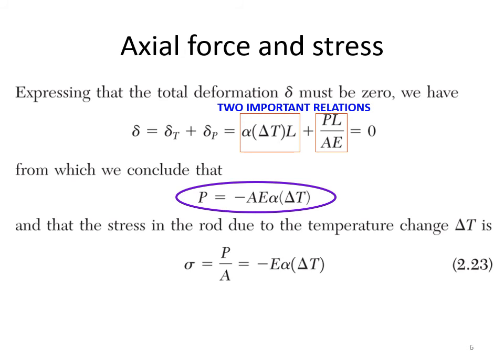The total deformation, elongation during heating and contraction during pushback, must be zero since the rod is constrained. Our desired solution is shown in the middle of the page.